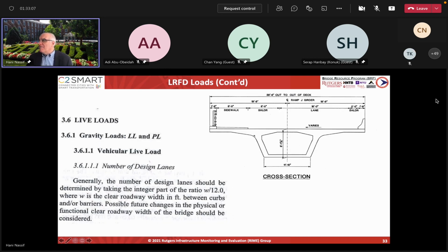And for the live load, you really need to look at, you don't look at the traffic lane. We look at design lane, meaning that it doesn't matter if you have only 2 traffic lanes and 2 shoulders. As long as you can fit a truck with a certain arrangement, 6 foot and then 4 feet and then another 6 foot, another truck and so forth, and the uniform load will be everywhere, then you have to maximize your total moment based on the number of design lanes.